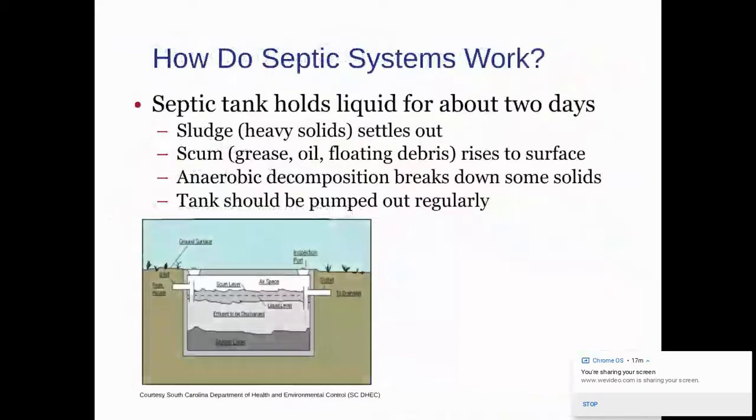Septic tanks. Basically, the concept is, from the left, the inlet, you have the septic stuff coming in. It falls into the tank, and then all the solids fall to the bottom, and the liquids stay up at the top. You have an air layer, a scum layer, and effluent to be discharged, and then all the liquids will go to the outflow to the drain field.